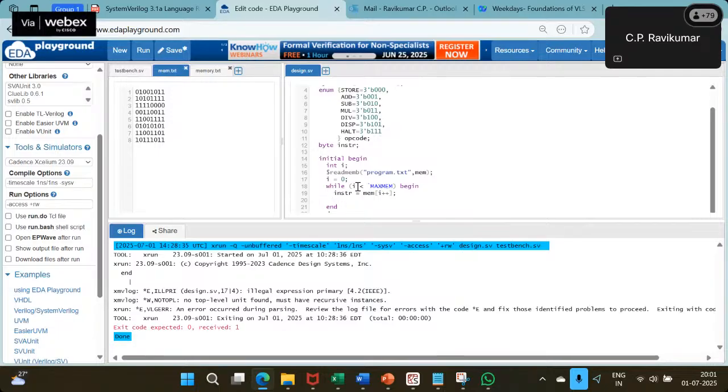So the last 7:7, 6, and 5. Okay. I would have loved to use alias here, but I think it is only allowed for wires. Okay. So unfortunately, this is not a wire. So as a result, I can't directly use that. Okay. So we could say if you want opcode equals... op equals this.